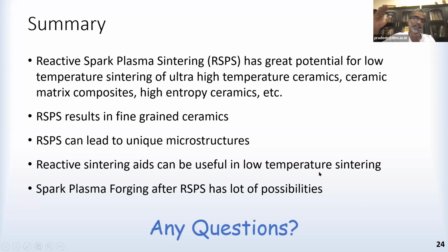But specific orientations can come in probably other crystal systems. We found that is true. We found that when we add ZrB2, we get fixed texture. When we add GNP, graphene nanoplatelet, we find texture happening. But otherwise, it is not textured.